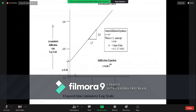So we have to convert the accumulated time into log time, and the accumulated infiltration into the log value of that accumulated infiltration, and develop a graph. From this graph, you can get the intercept a equal to 0.44. From the slope, you can get n, and finally y is equal to a t to the power n. Now you know the a and n values, and you can create this type of standard equation. This is for the data computation purpose.